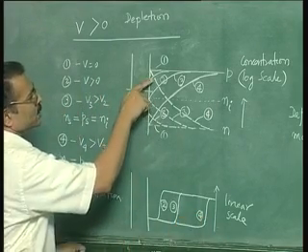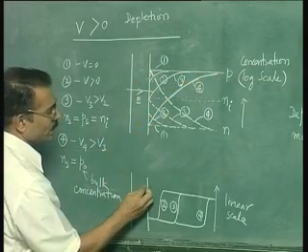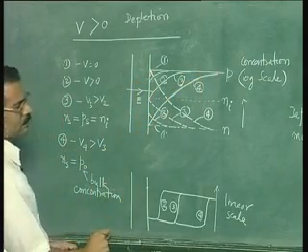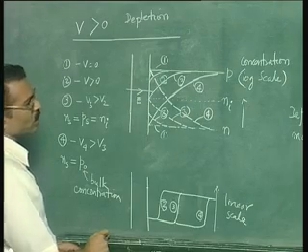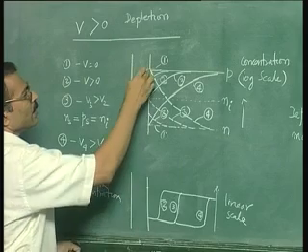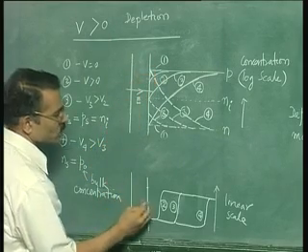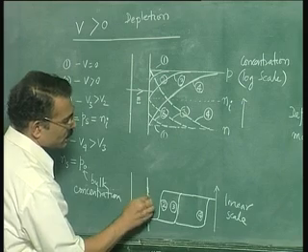But now, since this electron concentration here is equal to the hole concentration inside, you can show the electron concentration also. When you plot the electron concentration on a linear scale, in a small region it would have fallen by a factor of 10. So here this electron concentration will look like this.